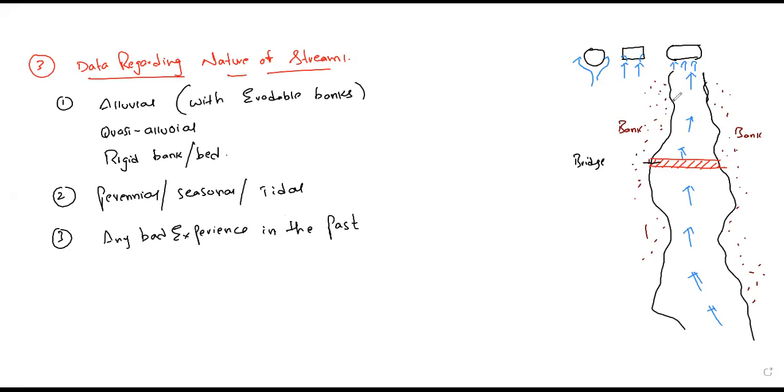If there are already old, small bridges crossing this obstacle, whether those bridges have been damaged due to heavy tides or heavy monsoons, that information about bad experiences also we have to know before designing the new bridge. Understand? Right, next one, banks at the proposed site can be banks.